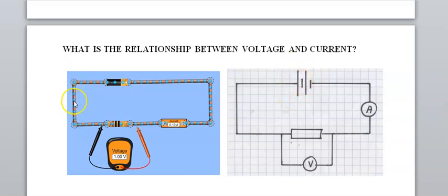It will have some wire, copper wire like this. We draw copper wire just as a line like that. It will here have a resistor. There is a resistor. And it will have an ammeter in series with the resistor. Here is my ammeter in series. And in parallel with the resistor, there will be a voltmeter. The voltmeter will measure the voltage between the ends of the resistor, and the ammeter will measure the current that's going to flow through the resistor.